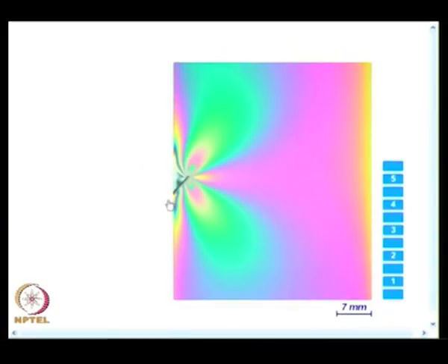In the case of mode 1 loading, about the crack axis the fringes were exactly symmetrical. Not only that, they are tilted symmetrically. The moment you come to a combination of mode 1 and mode 2, you find it is no longer symmetrical about the crack axis, observation number 1, and I would again load the specimen sequentially. Then you will observe the fringes on one side of the crack and other side of the crack are not of same size, which you could observe.